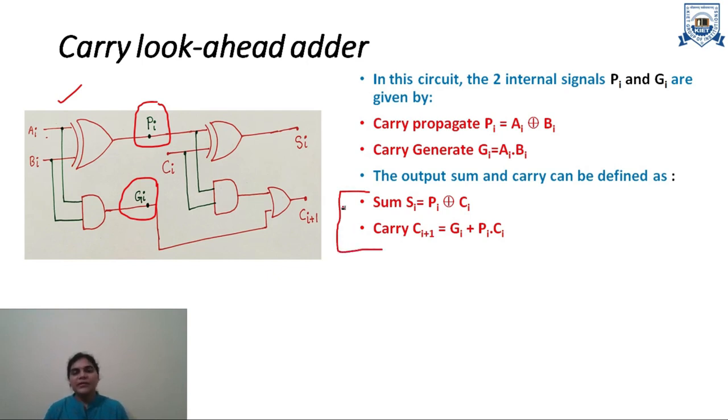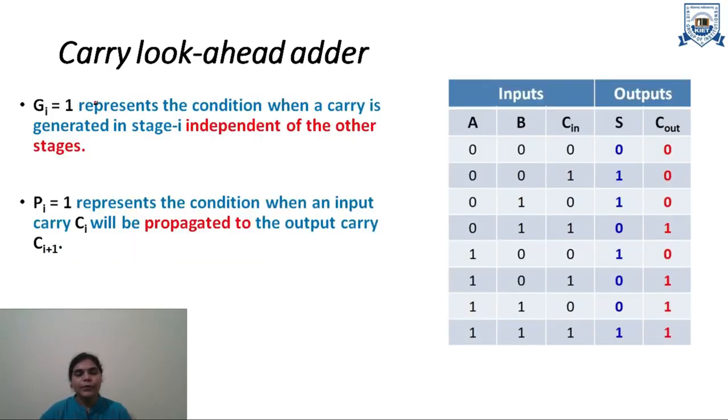Why are we doing this? Because these sum and carry equations will help us to design the carry-lookahead adder. Before going ahead, we first look at what the carry generate function and the carry propagate function are. The carry generate function represents the condition when a carry is generated at stage i, independent of other stages.